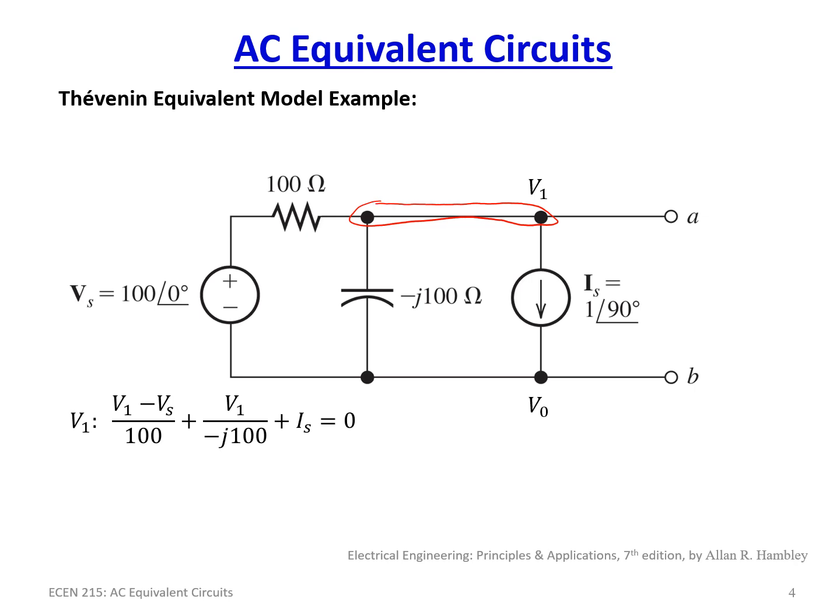Going this way, that is simply V1 minus the voltage at this terminal, which is Vs. So V1 minus Vs over 100 ohms. That's current number 1, going this way.